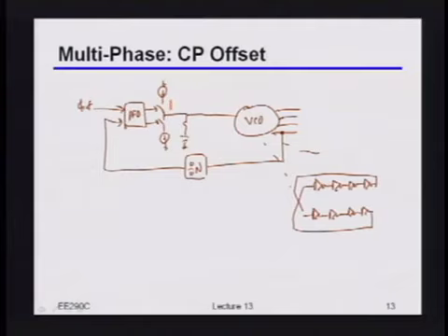And I'll give you guys a hint or a reminder. There was one particular thing that we talked about in some reasonable amount of depth that caused a problem with static phase offset. Anyone remember what that was? I heard somebody whisper it. Just have some mismatch on the charge pump current.